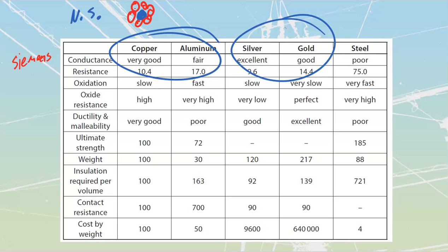We will use steel itself to deal with building enclosures, though. Obviously, it's a good hard material that, when properly powder coated, etc., isn't going to break down. So we do have to bond them together because it is still conductive. We'll talk about that in grounding and bonding.